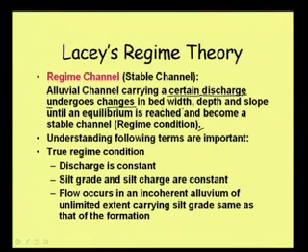Of course, when I was explaining, I did not mention the slope. The slope will also get adjusted. When the velocity is more, it will be eroding and the slope may get increased. When the velocity is less for that particular discharge, sedimentation will occur, and if the sedimentation starts from downstream, then the slope can reduce.